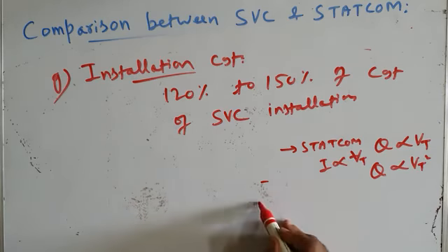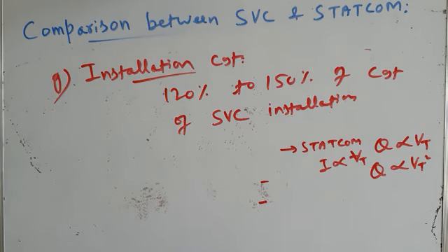Third is capability to exchange real power. In addition to exchange of reactive power, STATCOM has the capability to exchange real power also. And this feature is not there with SVC. So this point also goes in favor of STATCOM. Fourth is physical size. The physical size is smaller.